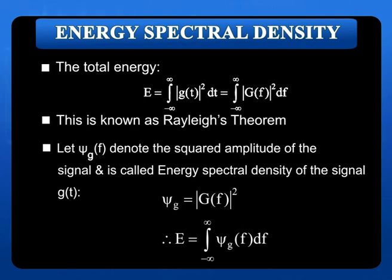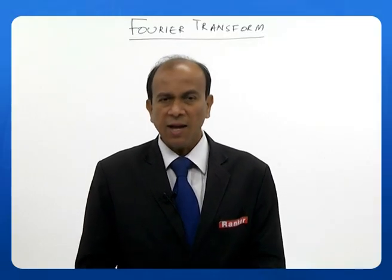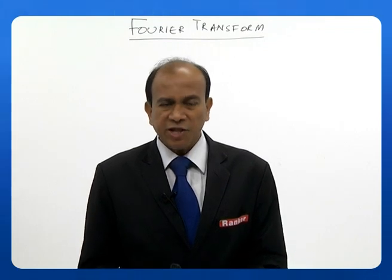Therefore, the energy can be written in terms of energy spectral density. Therefore, energy is equal to the integral from minus infinity to plus infinity of psi g of f df. But what is psi g of f? As we all know, we have defined it as equal to mod g of f whole square. So this psi g of f is called the energy spectral density.